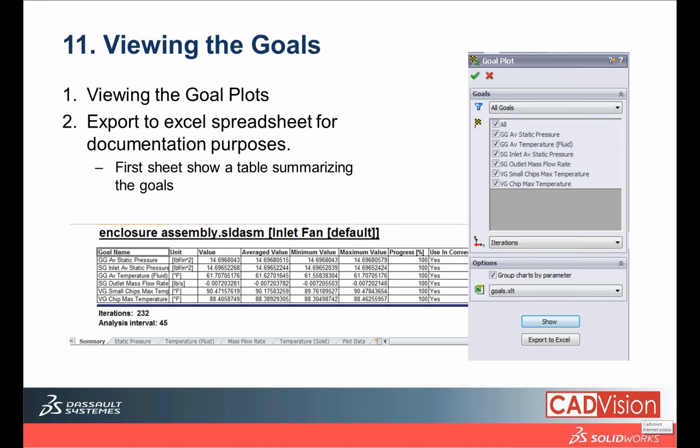Then the next will be viewing the results, the post-processing of our study. First of all, we would like to check the goal plot. You can view the goal plot, checking on each of them, and click on show.